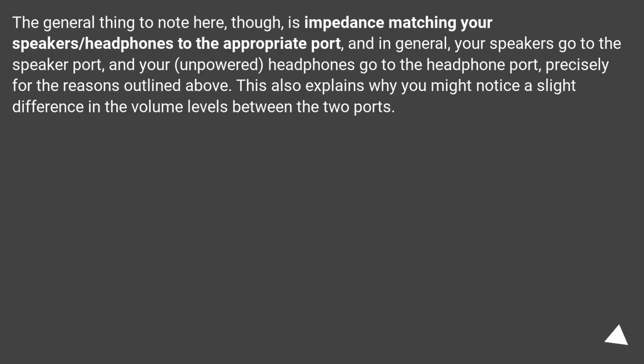The general thing to note here, though, is impedance matching your speakers/headphones to the appropriate port. In general, your speakers go to the speaker port, and your unpowered headphones go to the headphone port, precisely for the reasons outlined above. This also explains why you might notice a slight difference in the volume levels between the two ports.